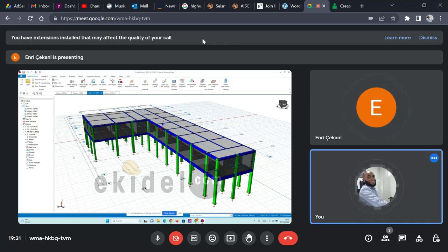Also, let me use this medium to explain the joint between the column and the beam. If maybe you are using a link spacing of, let me say, 175 millimeters for your columns, when you come to the joint between the beam and the column, for some percentage on the beam you have to use the same spacing you use for the column, but not throughout the beam, only to some certain percentage. I don't know if you get what I mean. Yes.